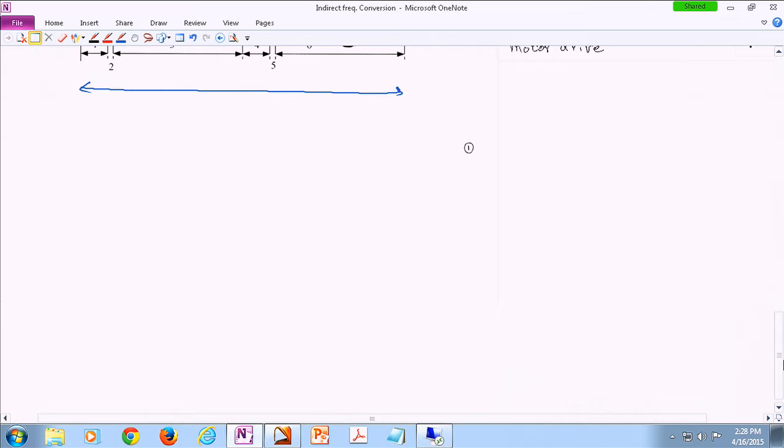In fact, generally we open the circuit breaker in an AC circuit when the current is zero and voltage is maximum. So if we are opening our switches when the current in a particular phase is not zero, then there will be current chopping. Your input currents are discontinuous, because you're jumping from one current value to another, like from 10 amps to 0 or vice versa. Then you need some sort of low-pass filter to make it palatable to your input, whether it is the power grid or your generator.